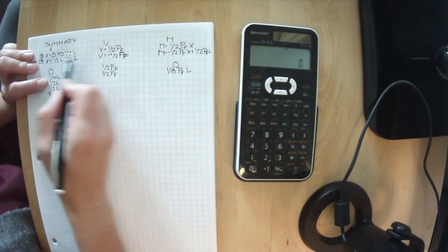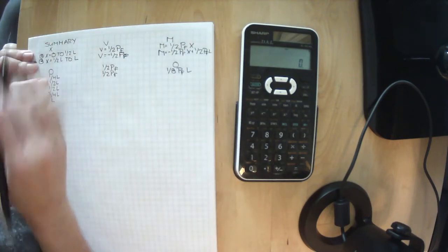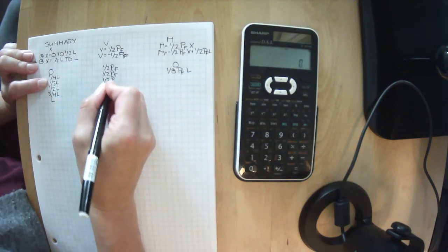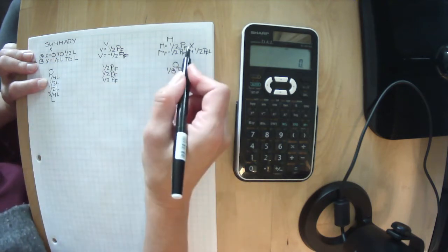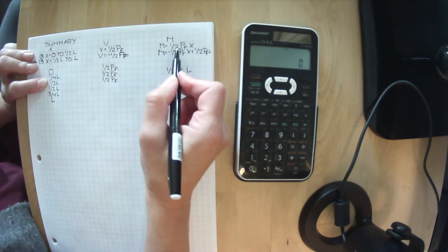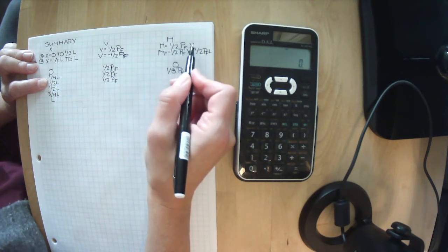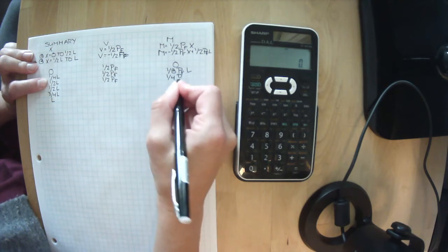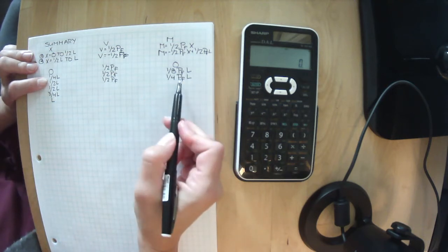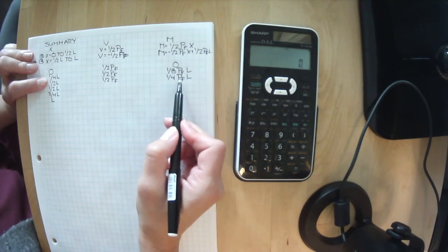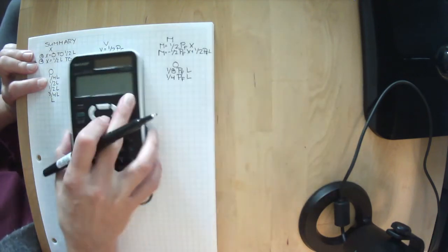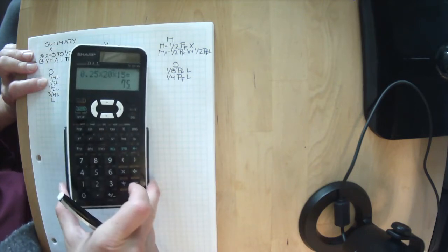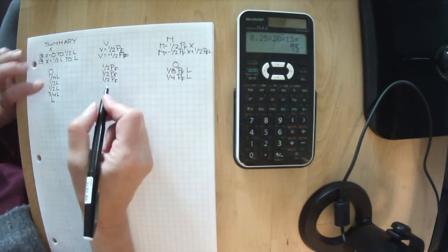Okay, let's do 1/2 L, but on the left side of the beam. It doesn't matter, our shear stays the same. It's not dependent on x. So 1/2 L being plugged into x, we have 1/2 PF times 1/2 L. So half times a half is 1/4, 1/4 PFL. Or that would be, in our last example, 1/4 of 20 times 15. So 0.25 times 20 times 15, 75 kilonewton meters. So that seems to match up.